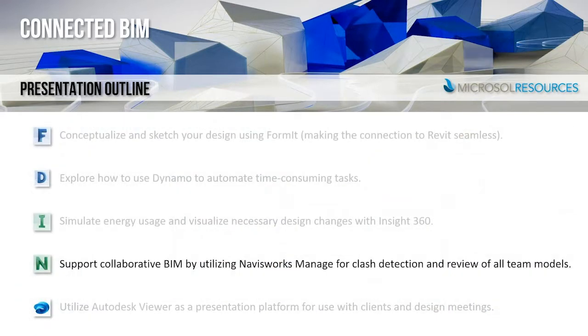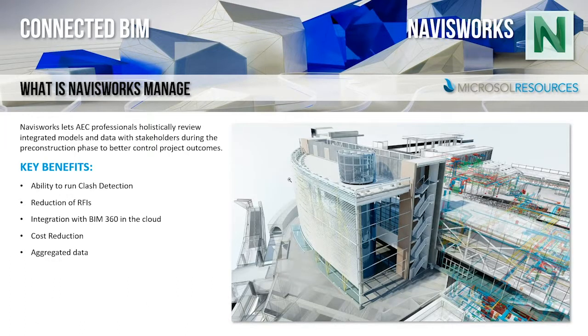So we've covered how to use Formit, Dynamo, and Insight in conjunction with Revit. Now let's take a quick look at Navisworks Manage. So for those of you unfamiliar, what is Navisworks Manage? It's a software that allows AEC professionals to combine and coordinate models and data from multiple resources in one holistic file for review. It is not a 3D modeling program, but a program that converts large Revit models into smaller models that are more manageable with multiple team members.